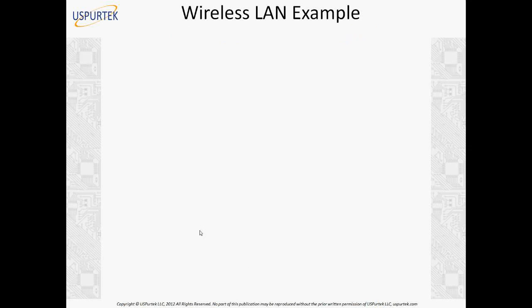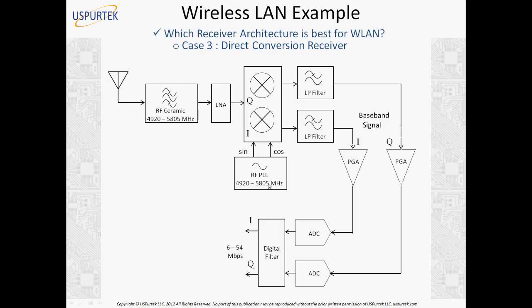What is the downside of the DC component here? The DC component can change the operating point of the amplifiers. The operating point is set at a certain middle point, which keeps the signal variations within the linear region of the amplifier. But if you have a DC component, it will shift the operating point of the amplifier, causing the signal to overshoot into the non-linear region of the amplifier, and that gives rise to distortion. So we have to deal with this DC offset in this case.